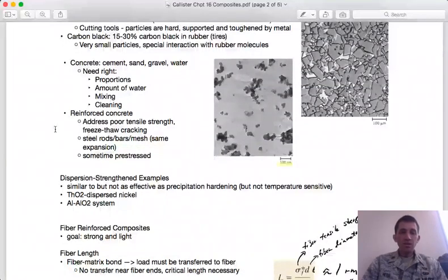Steel makes a good match, not only because of its ubiquity, the fact that you can get it relatively cheaply, its availability, but it also has a similar expansion rate as the concrete, which keeps it from disrupting the interface from different coefficients of thermal expansion over time.